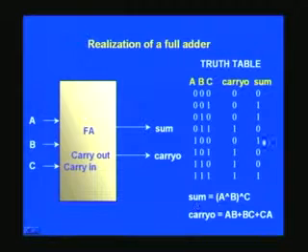And hence this expression is nothing but this. The reason this bracket is put is that in Verilog we can implement this using gate level primitives also. They are restricted to 2 inputs basically, and so in order to realize a 3 input exclusive OR, you will have to use 2 numbers of 2 input exclusive OR, and carry out is simply a majority logic, and you can easily infer the majority logic wherever more than 2 ones are there. There you will see the corresponding 1 here. You can see it here everywhere.